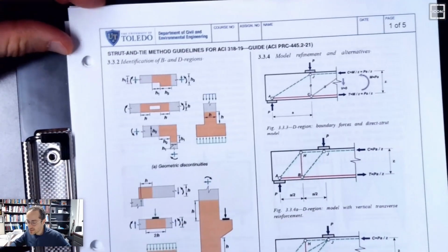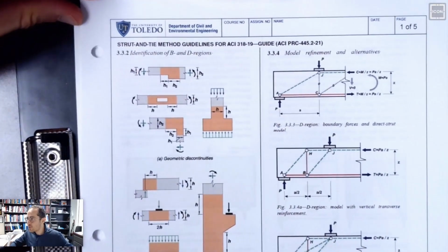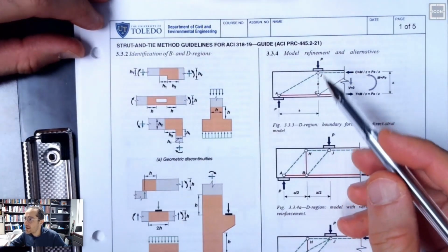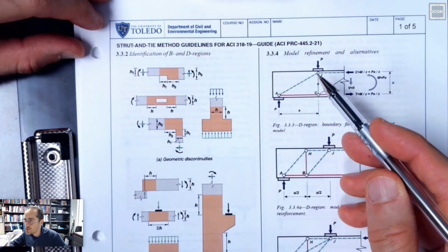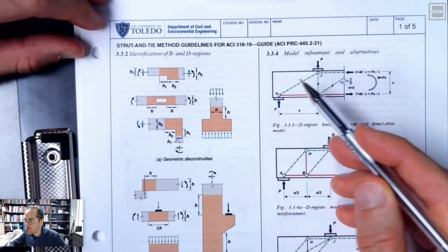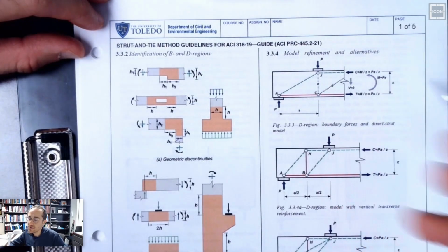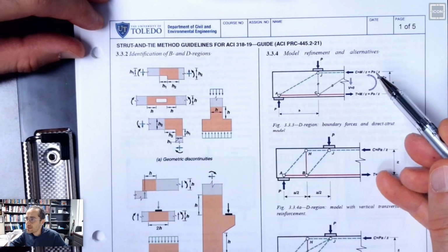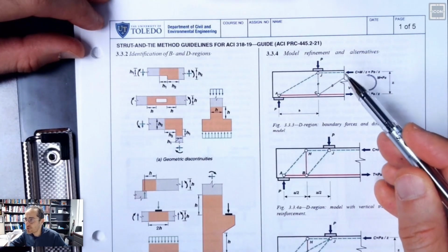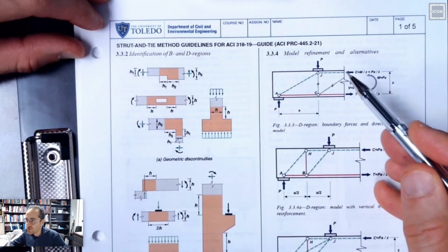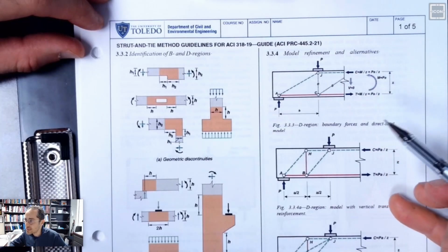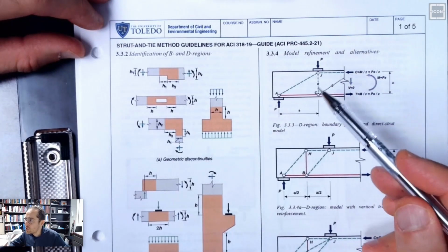This also discusses a couple of strategies for model development. In the first attempt, if the angle is not too shallow, it always makes sense to use a single strut and see whether it passes or not. That should be the first attempt. Again, the code is using the stress block approach, calculating the moment to help determine the centroid of the rebar as well as the centroid of the strut. So you can see this approach. So you do this first.